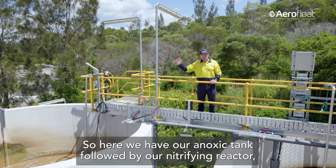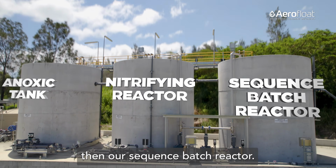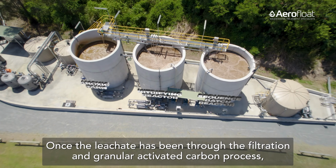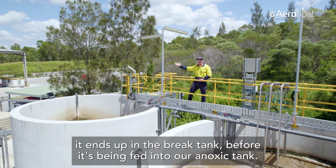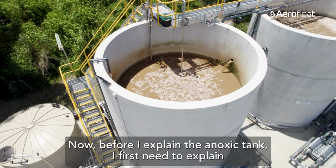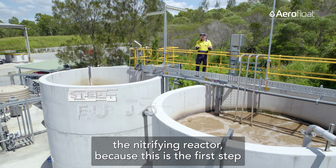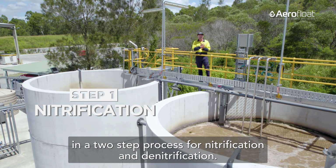So here we have our anoxic tank followed by our nitrifying reactor, then our sequence batch reactor. Once the leachate has been through the filtration and granular activated carbon process, it ends up in the break tank before it's being fed into our anoxic tank. Now, before I explain the anoxic tank, I first need to explain the nitrifying reactor, because this is the first step in a two-step process for nitrification and denitrification.